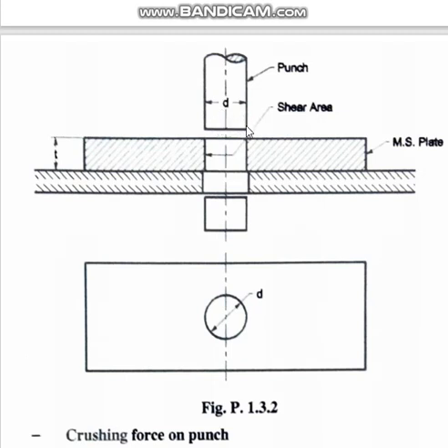How do you know that this is circular? By what type of break it is having. If it is broken like this, then that means it is circular. The circular punch is here, and if you bring it with much force, with hammer force, and pierce or punch through this, it will cut like this, and this cylindrical piece will fall off.